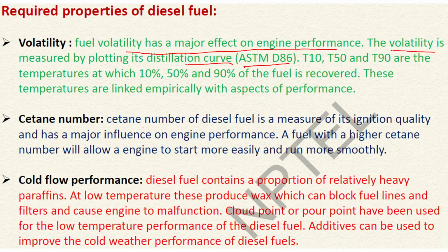The cetane number of diesel is a measure of ignition quality and has a major influence on engine performance. As I told, the cetane number should be high. That means the delay time from the ignition to the combustion of the diesel fuel inside a diesel engine should be as low as possible for the smooth running of the diesel engine. Then cold flow performance.